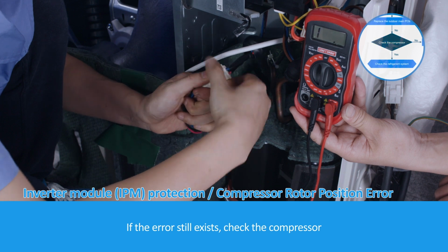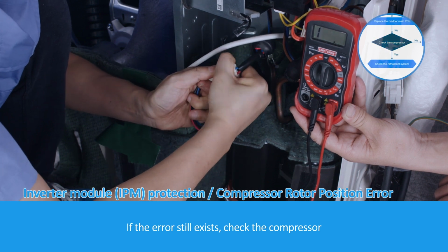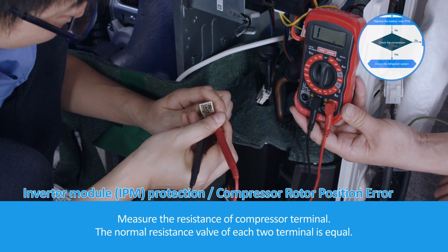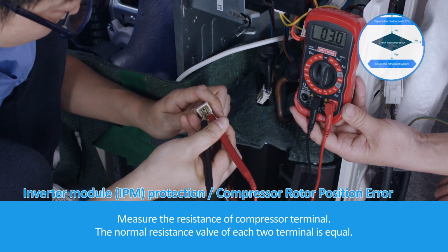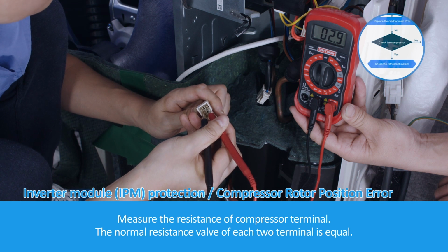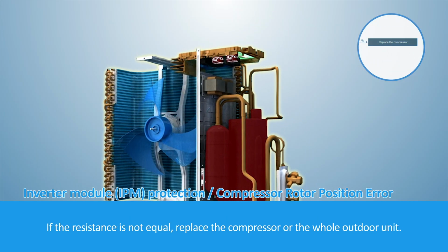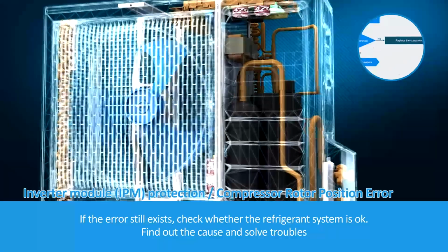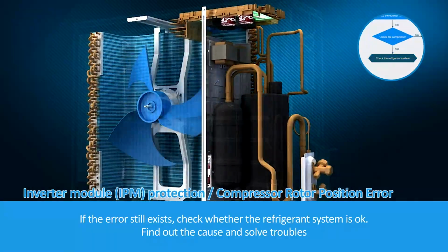If the error still exists, check the compressor. Measure the resistance of the compressor terminals. The normal resistance value of each two terminals is equal. If the resistance is not equal, replace the compressor or the whole outdoor unit. If the error still exists, check whether the refrigerant system is okay. Find out the cause and solve the troubles.